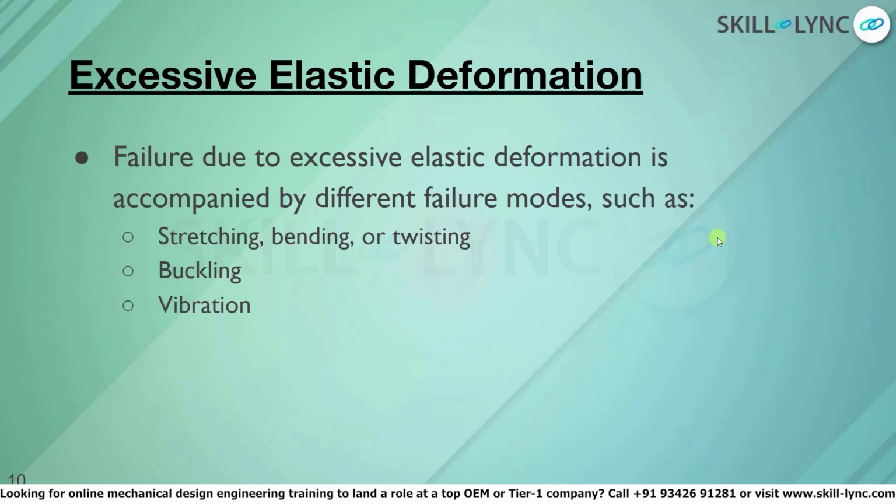As for excessive elastic deformation, this deformation is accompanied by different failure modes. These failure modes can be stretching, bending, or twisting, buckling, and vibration. Although these aspects are called elastic deformation and are known to recover, in practice the material never fully recovers.